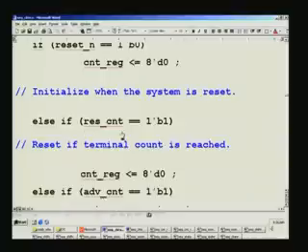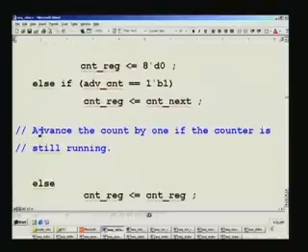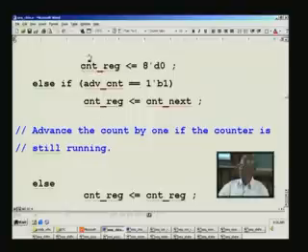And this also corresponds to the counter register being 255, and then you need to make the counter 0, clear the counter, and you count only when advance count is active here. This was pre-incremented earlier, and we merely assign here in order to speed up the operation. If nothing else is satisfied, in fact all aspects are covered here, and so it is a dummy statement wherein you do nothing, just preserve its contents. If you dispense with this, then also it will work.